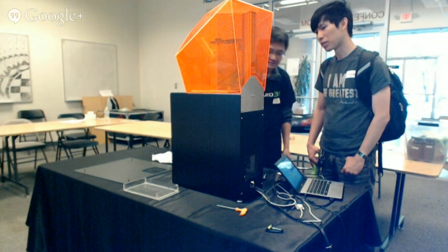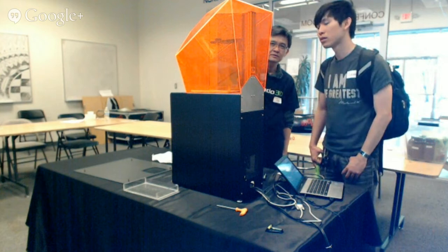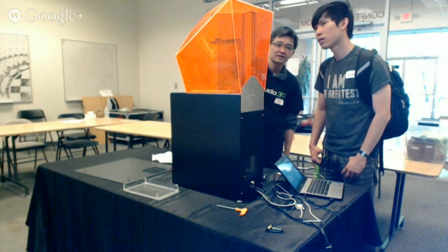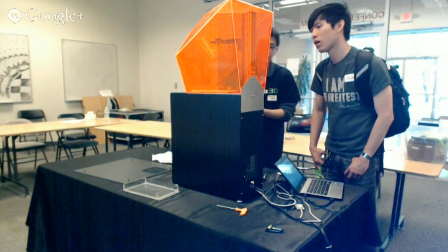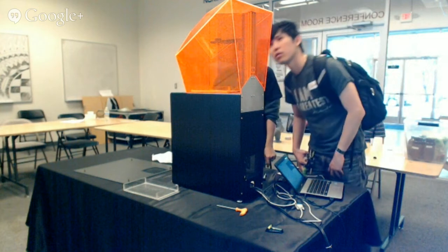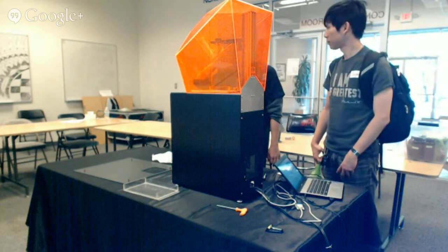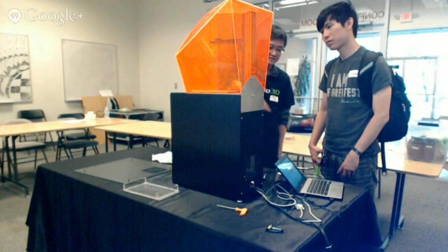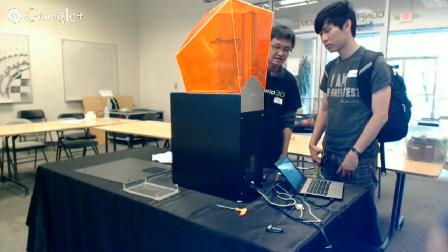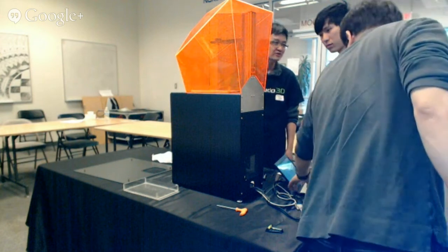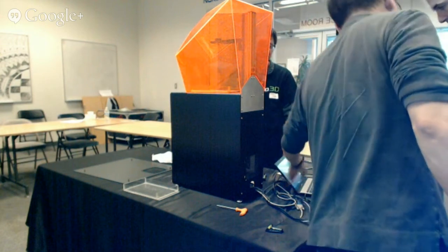One of the things is that compared to other printers, mainly because of the way the stickiness works for the Teflon, there's more of a reason to have many different layer settings for this, where you have an exposure setting for layer 1, different exposures for layers 2 to 8, and different ones for layers 9 to 100.